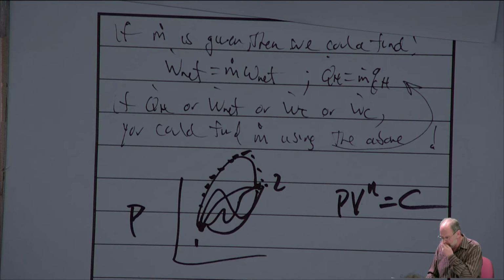Real quick, can you go over the sign convention for work and the Q term in the first law? Okay, so the first law is a general equation, and we have to respect the various signs within that equation. But there's also a sign convention that has to be covered. If you look at this material in your textbook, the author likes to talk about heat in, heat out, work in, work out. That's fine, but I prefer to think about it as heat or work with the appropriate sign. If heat is added, heat into the system is positive, and if heat is lost, heat rejected from the system is negative. Work is actually the opposite of that.